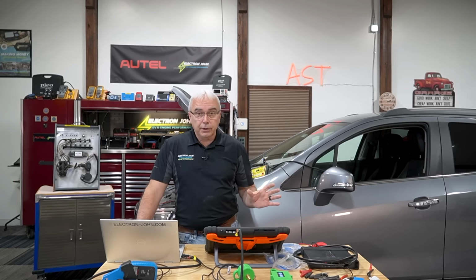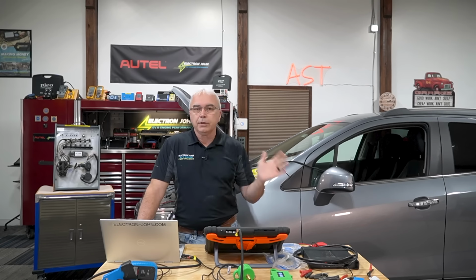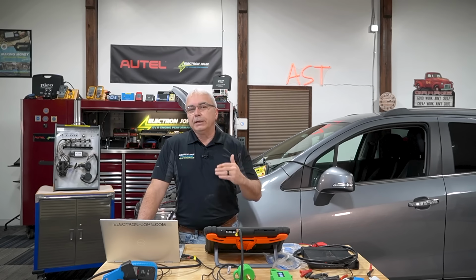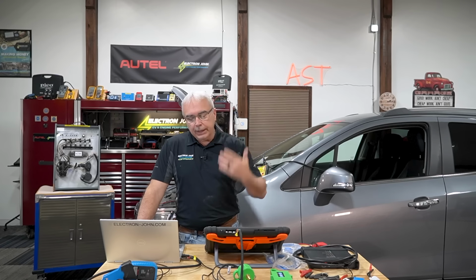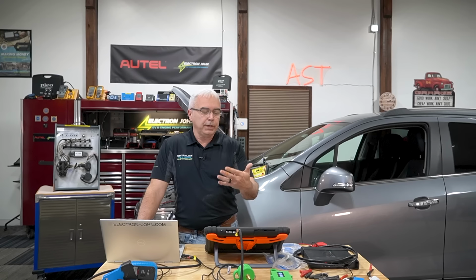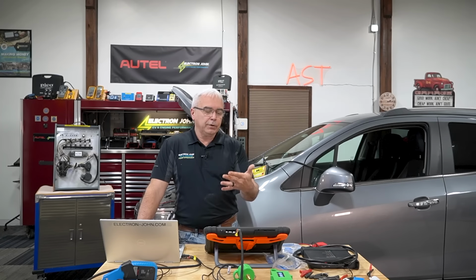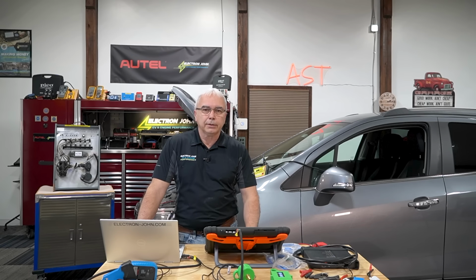and I see that my intake air temperature sensor, no matter where it's located, whether it's in an intake manifold or inside of an air cleaner housing, I don't care where the manufacturer put it, if I start to see that getting too high, right? So if I'm looking at my scan tool and it's got a lack of power type of complaint, or maybe it's running rough, or whatever the scenario happens to be, and I look at my intake air temperature and I see that that's 180 degrees, we'll just throw that figure out there.